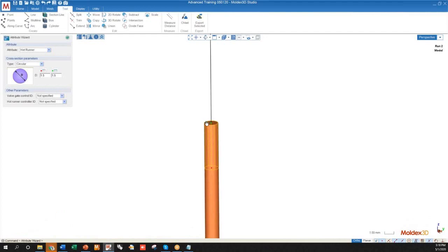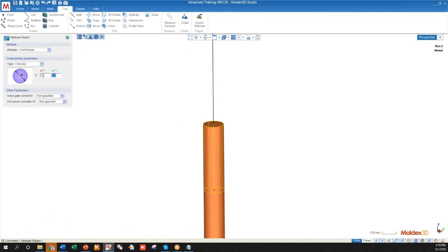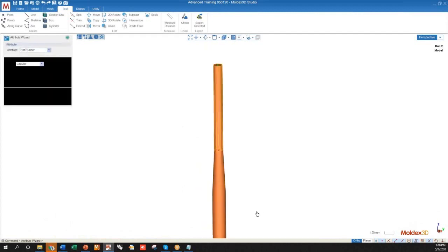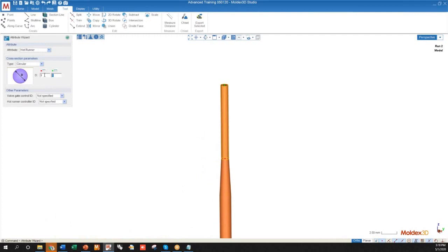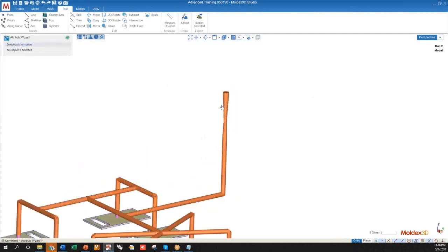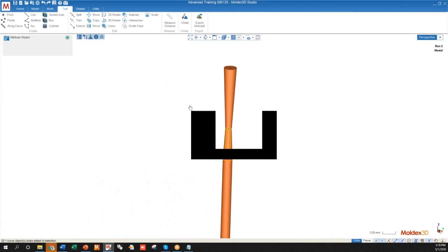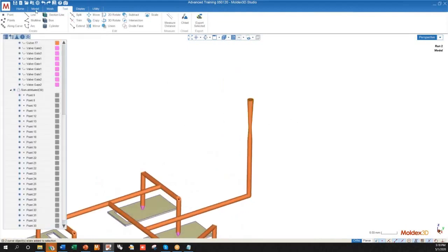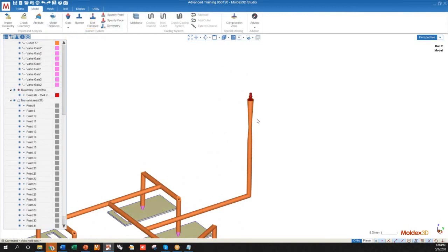We will always have a hot runner attribution for the nozzle. So let's say I have a taper like this. And hot runner, and we'll take it out to, let's say, the green end here is going to be 2. So let's say we have a nozzle situation that looks something like that. And then I would simply just reassign my melt entrance, which should be pretty simple.